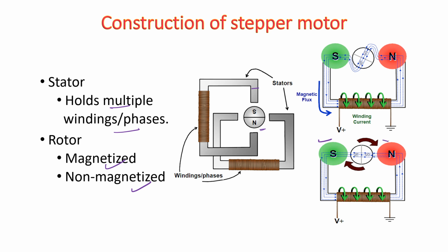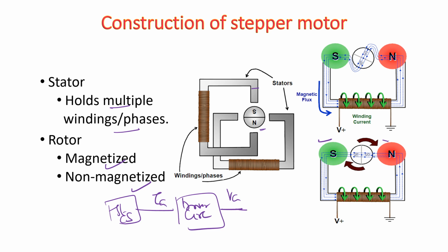Let's see, once again I will repeat. This is a joint control system. From the joint control system, it provides the torque. This torque is given to the driver circuit. Then the driver circuit will produce the armature voltage, Va. Then that is given to a motor, any motor, and then that is given to the joint. This is how it works.